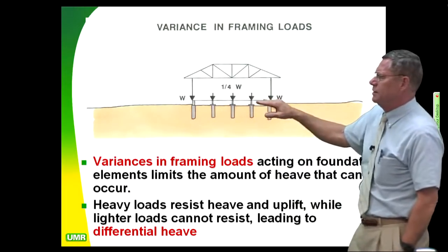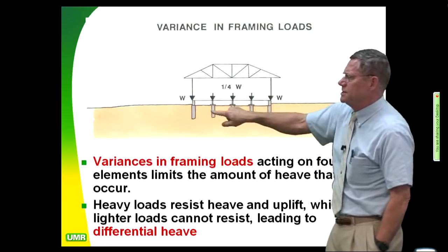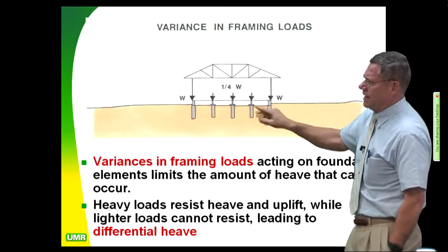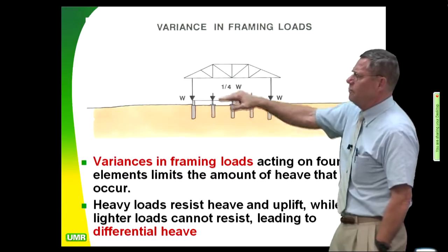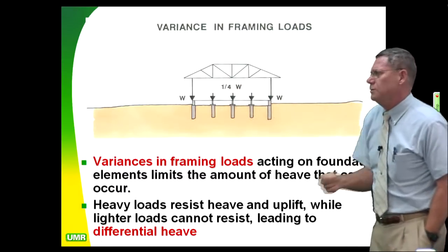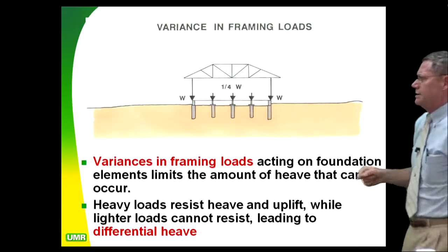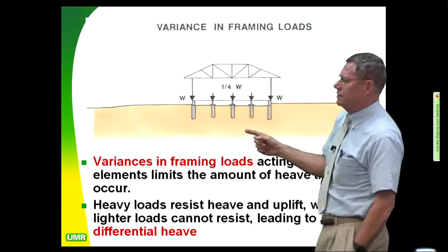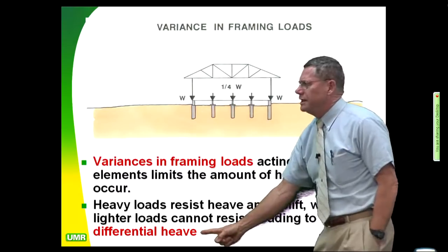But that can also lead to differential heave, because these guys aren't going to get as much load, so they're not going to heave. They're going to tend to heave more than the ones next to them over here. Now we're going to talk about this over and over and over until I think you get it. So our enemy in geotechnical engineering is differential heave.